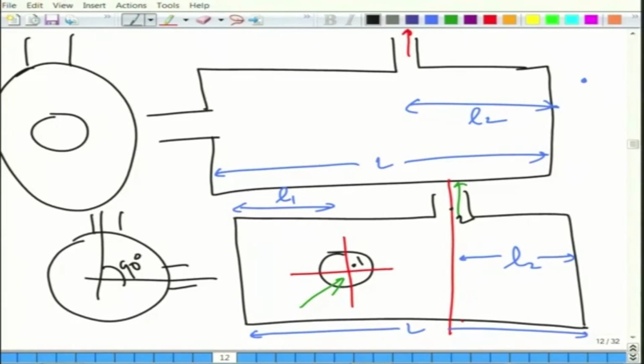We will show how, because of the cavities that are formed, they are like quarter wave resonators, the cavities that are formed between the port and the end face. And the cavity formed here in the chamber shown on the top also acts like a quarter wave resonator, and this is a plane wave propagation path. So this system acts like an expansion chamber muffler with just an extended outlet or an extended inlet, in case this is the inlet and this is the outlet.